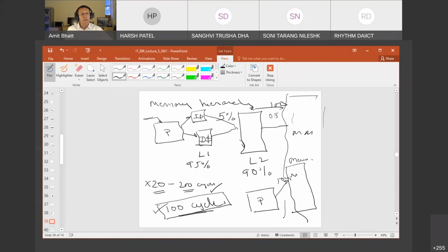If there is a data dependency between the first and second instruction, it is always going to be there, and it is always going to take extra time. So you account for that. In a real-time processor, this is what they have to do. All automobile processors are real-time processors. Most of the time, for example with fuel injection, the car wants an answer within a certain amount of time. It can't afford that your processor is hanging.